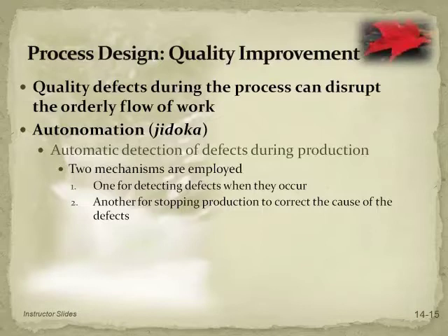And if you have 400 wires in a wiring harness, that means that you have 800 wire ends in that harness. Each wire has 2 ends. And that means that you have 800 opportunities for making a mistake in connecting that wire in to wherever it goes. So our process before Jidoka was to assemble the wiring harness and then to send it to a machine that did an electrical test to see if everything was connected correctly.